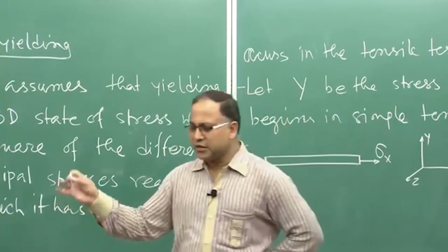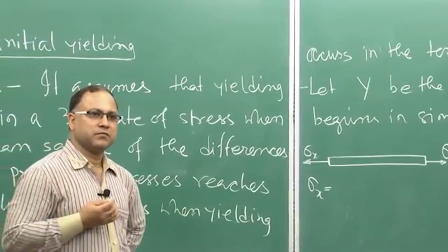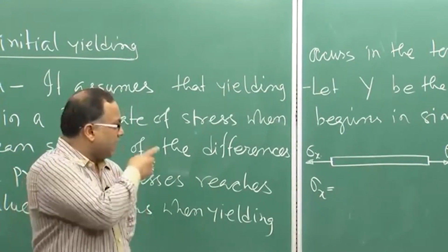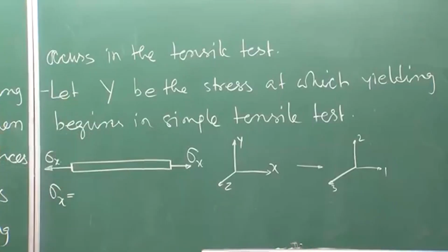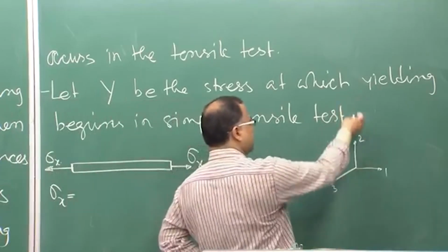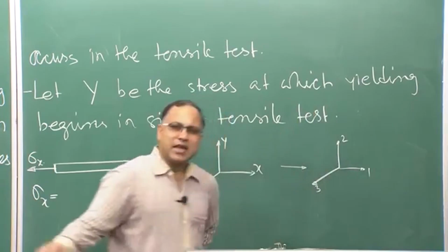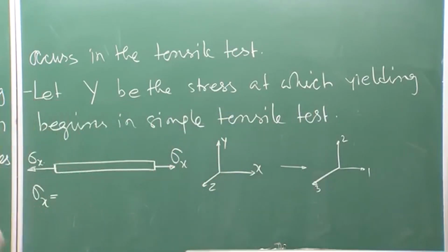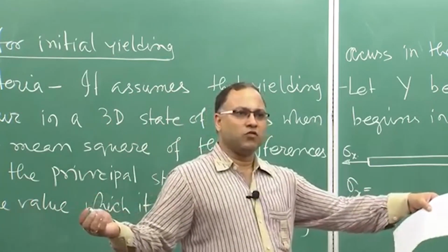If shear stress is 0 on a particular plane, that plane must be one of the principal planes, is it not? So the y plane is also a principal plane, and the y direction is becoming one of the principal axes, that is axis 2, and so on. And the z plane is also, because we are only applying a unidirectional tensile force, right.